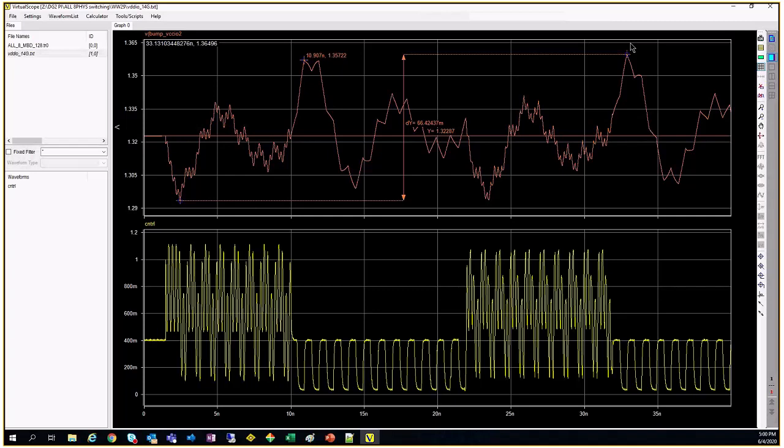Some AC spec. So plus or minus 2%. So it doesn't mean it should be like 40 plus, below also 40, above 40. Totally it should be 80 millivolts. It should never cross your peak to peak voltage. Okay. So this is this important spec, which we look in time domain. Right. So this is only one time. So for a given time, when you apply a current profile and you measure the voltage.